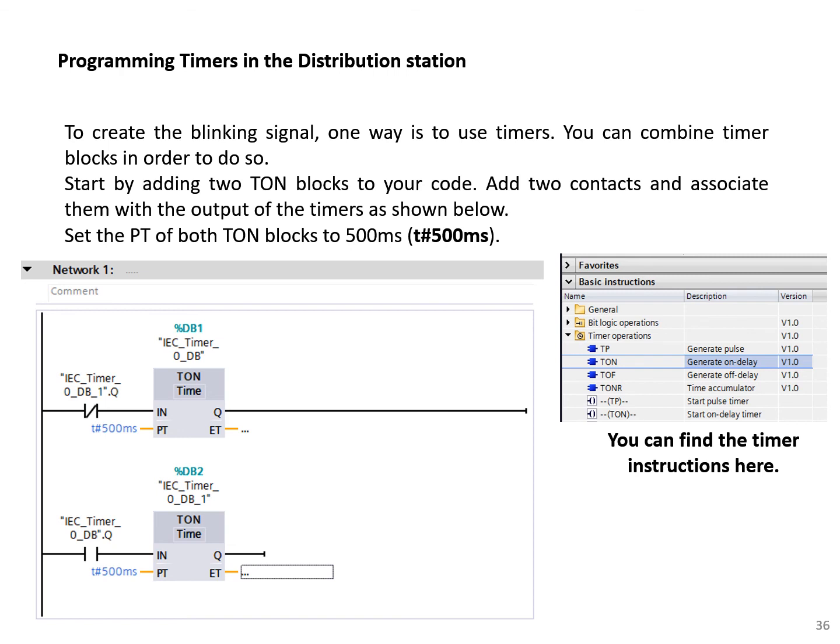Of course, once you start to create the project, you should choose ladder logic programming for the programming environment, and once you do so, then you have access to this specific environment, and in network 1, drag and drop 1 timer. Once you do that, and when you give it a name, you will have 1 instance of a timer in your memory and under your tag tables.